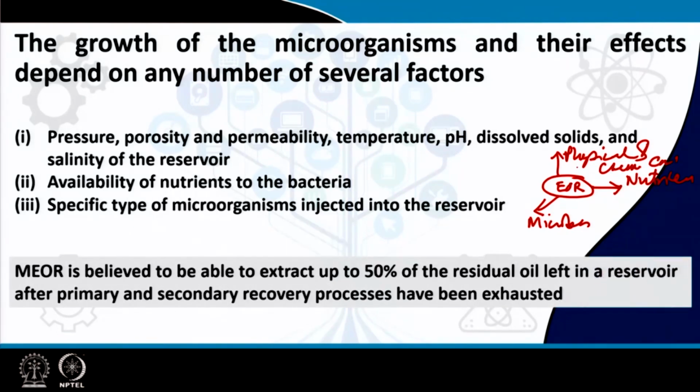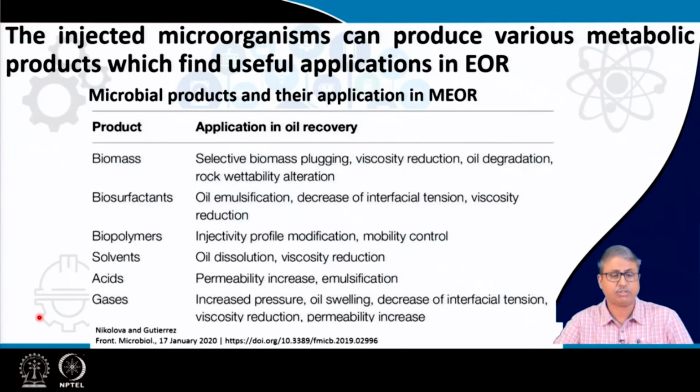Now, MEOR is believed to be able to extract up to 50% of the residual oil which is left in the reservoir, even after the primary and secondary recovery processes have been exhausted. So, once the primary and secondary oil recovery processes are done and it is found that it is no more suitable even for the secondary oil extraction procedure, then this microbially enhanced oil recovery is done.